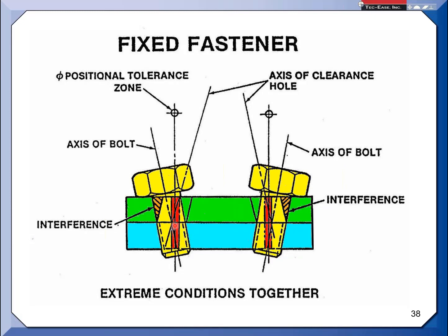What we're showing you here is that if you did keep it in the material, this tolerance zone appears at the clearance hole. So you can see that if manufacturing did produce the hole and it tapered within the tolerance zone, the axis of the threaded feature could still meet the requirements, but yet when you project the bolt out, guess what happens? If you didn't do a projected tolerance zone, you could possibly have an interference condition.